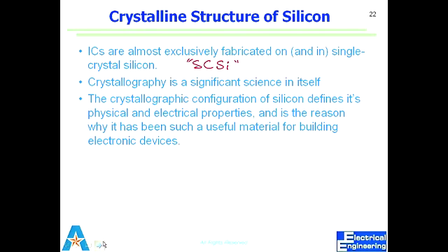Make sense? Why would you ever want to use polycrystalline silicon? It seems unwieldy. So it's a very fundamental, very important question. Polysilicon can be heavily doped. It acts almost like metals. Okay.